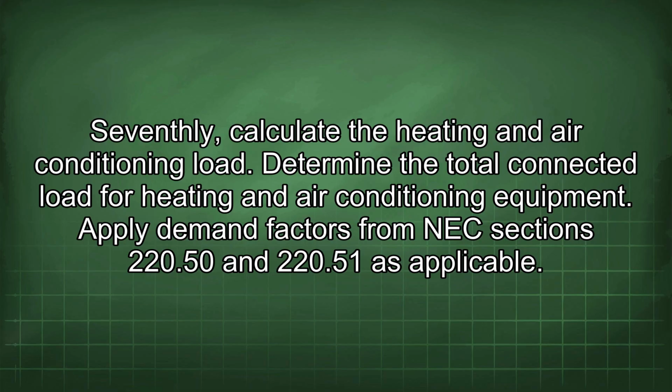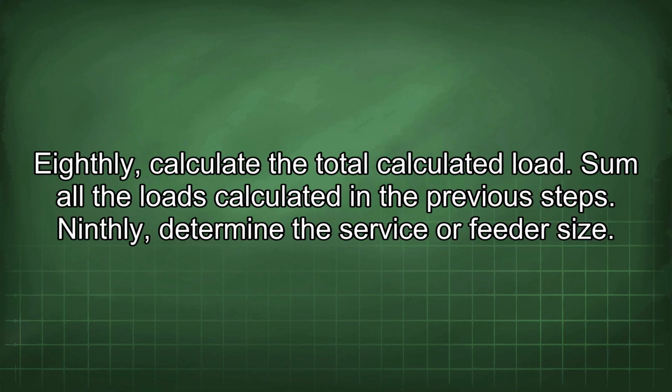Seventhly, calculate the heating and air conditioning load. Determine the total connected load for heating and air conditioning equipment. Apply demand factors from NEC sections 220.50 and 220.51 as applicable. Eighthly, calculate the total calculated load. Sum all the loads calculated in the previous steps.